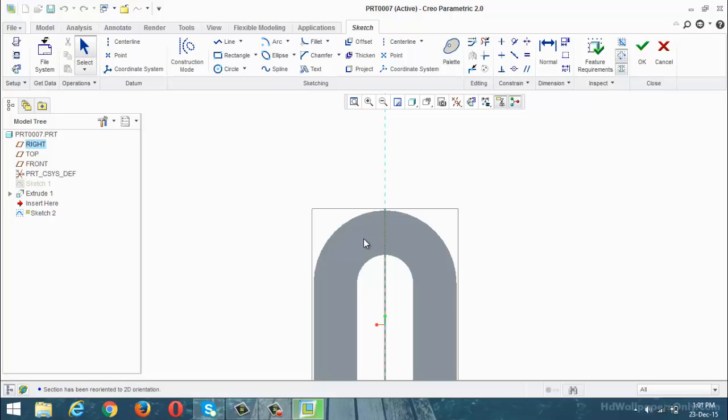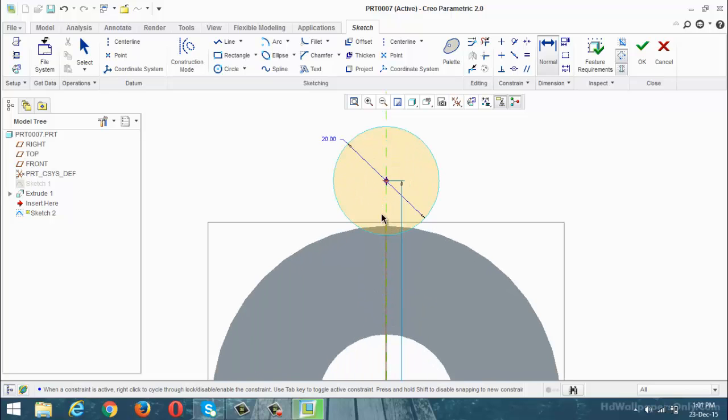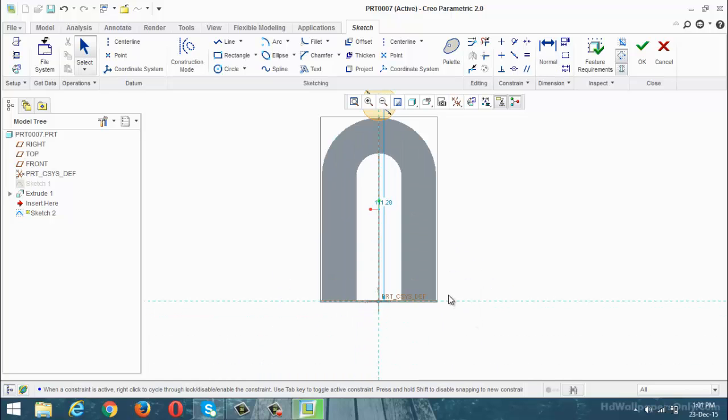Okay. Now I am going to design one circle in this location. See here. Now diameter equal to how much? 20. Diameter. This one is the 10R. 10R means 20. 20 means again you can change. Again normal. See here. Select this point. Select this point to. Okay, no problem. Already dimension will be taking place here. Again this one to this one.